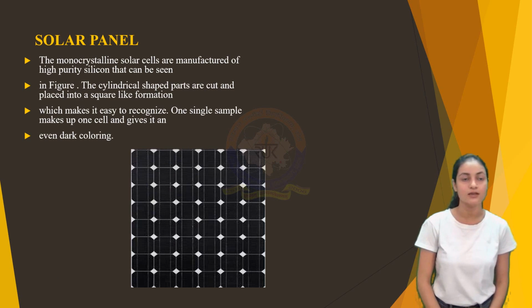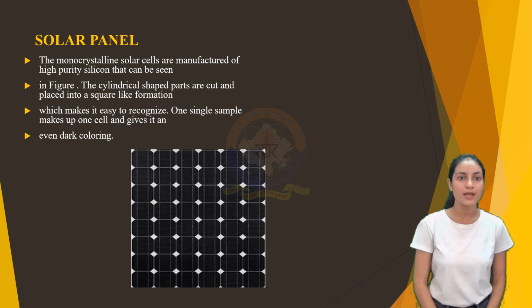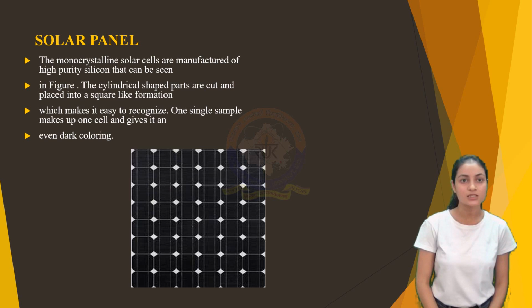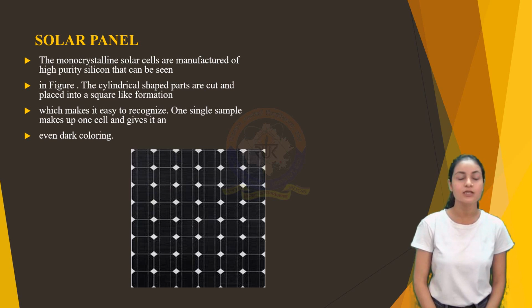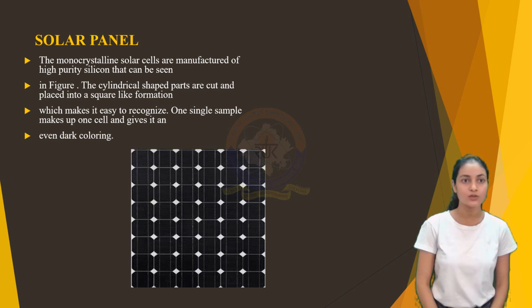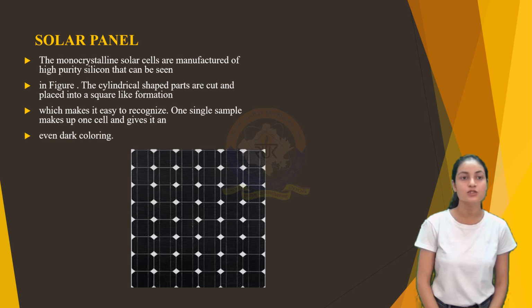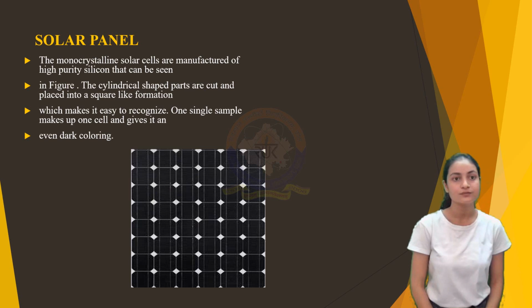Next is solar panel. The self-aligning solar panel uses a monocrystalline solar panel. The solar panel is partly for demonstration purposes, but it is also used as a measuring instrument during the second positioning mode. In this mode, the solar panel's output is continuously compared with the previous achieved peak output value until the entire celestial sphere is controlled. The highest achieved output from the solar panel is then stored for the self-aligning solar panel to reposition itself.